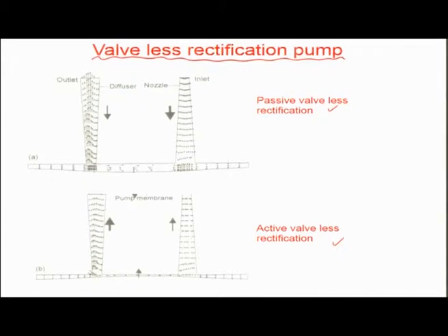The inlet side is like a nozzle, so the area suddenly increases, and therefore the increase in area would signify a reduction in velocity. Continuum assumptions lead us to conclude that an increase in area should always reduce the average velocity of flow, and therefore if the velocity reduces, through Bernoulli's equation, the overall pressure would increase.